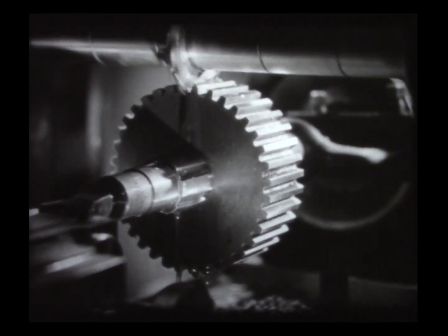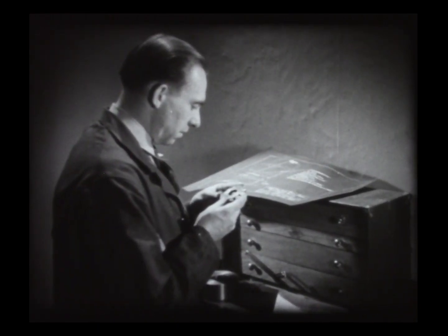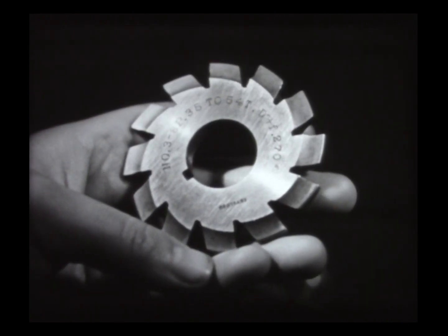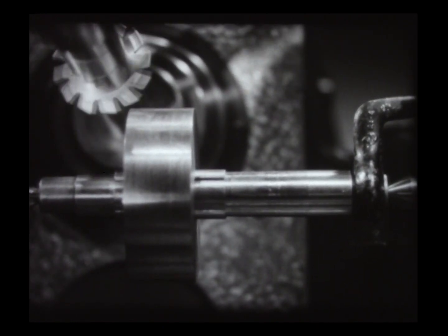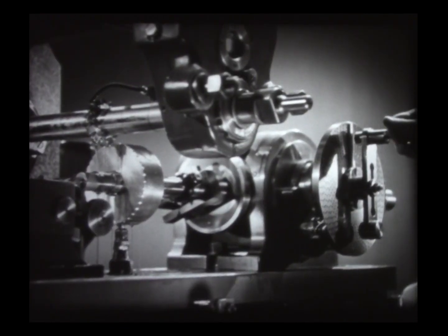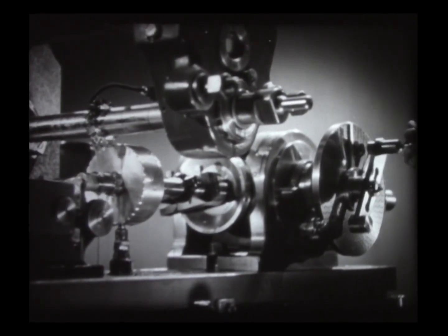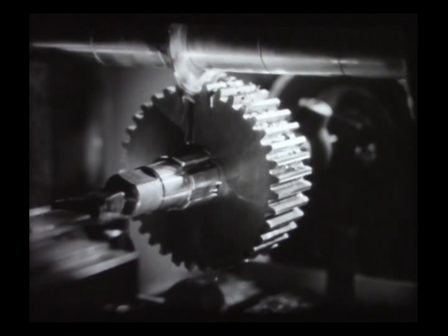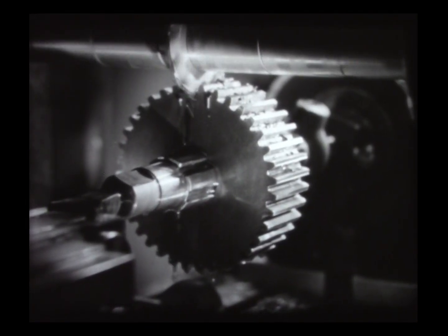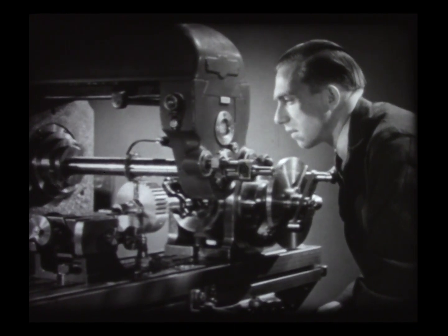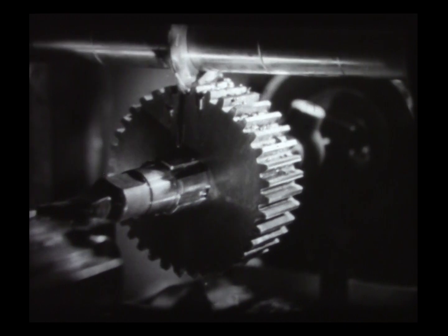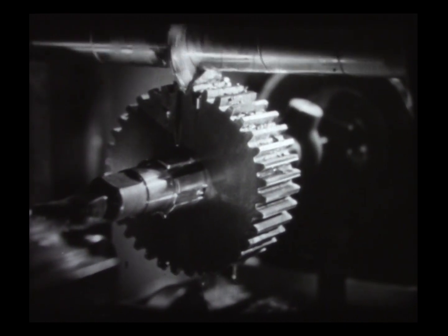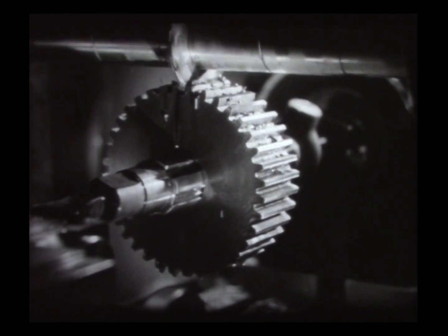For if the proper cutter is selected, a cutter stamped with the specifications called for on the blueprint, if both the work and the cutter assembly are rigidly set up, if the location of each cut has been accurately calculated with the dividing head, if the proper speed and feed have been set, and if the entire setup has been carefully checked before making a single cut, then the last step, actually producing the work called for, is a relatively simple procedure.